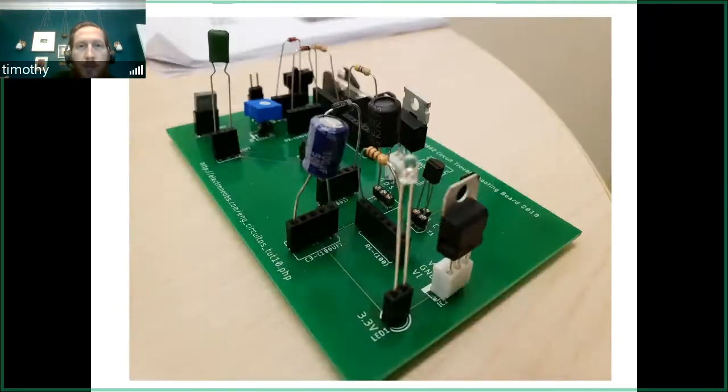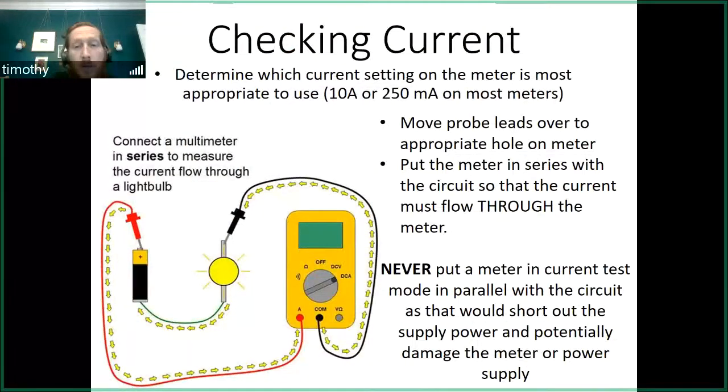So, checking current. We're going to talk about this a little bit because it's very important. Never put a meter in current test mode in parallel with the circuit, as this would short out the supply power and potentially damage the meter and the supply.